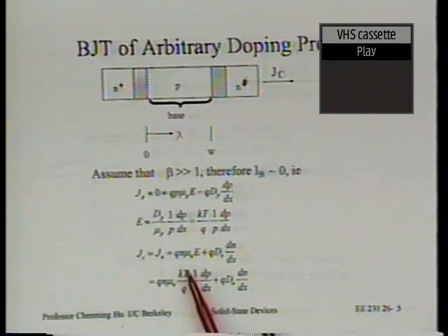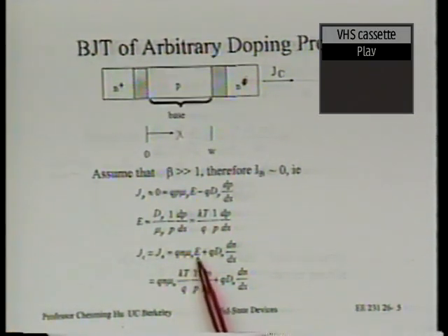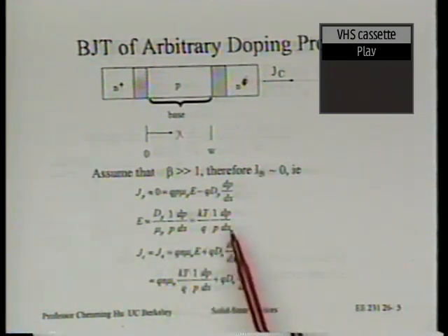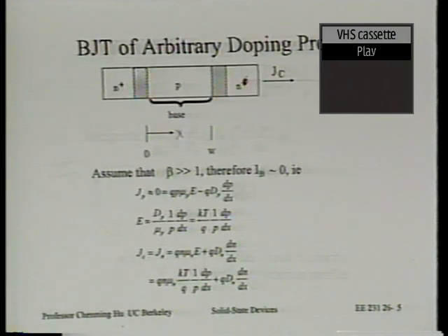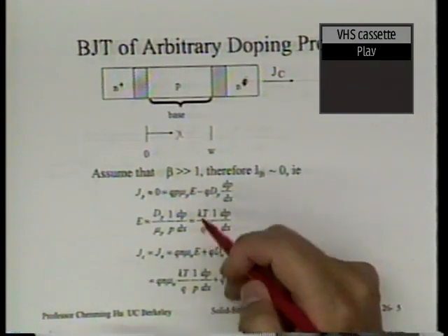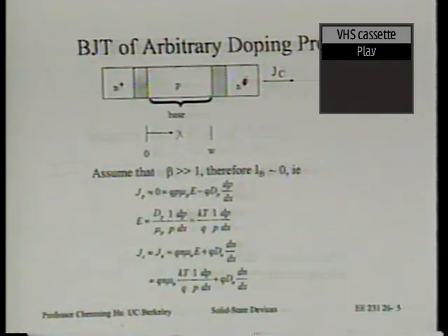Now here is where you're going to have to start making changes. If this is a silicon germanium model, then the electric field experienced by the hole is not the same as the electric field experienced by the electrons. So you probably have to say this one, we'll call this one the field experienced by the hole.